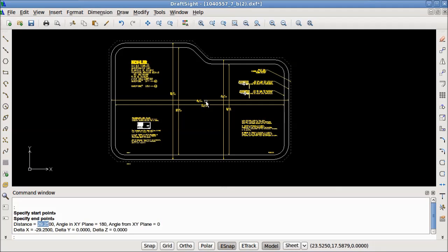Had this not been drawn in inches, we would have needed to either convert the drawing by scaling it, or were it in millimeters, we could have first scaled the drawing of our countertop to millimeters and then copied the cutout into the countertop drawing. So now that we've discovered the units in this drawing, we're ready to clean it up and prepare it for CAM. It is our suggestion that you copy what you need out of this file and paste it into another file, even if it's just a new and empty file. This is a fail-safe method that prevents unwanted entities from being sent from this CAD program to the CAM program and causing errors later on.